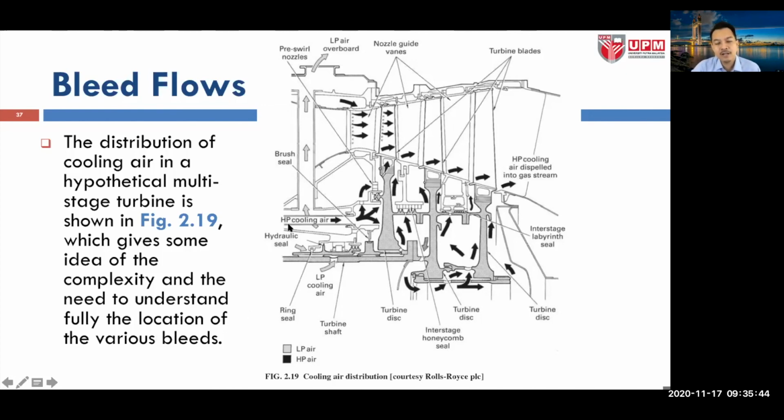Basically, the gas turbine engine designers, especially the internal cooling engineers, have to calculate the amount of high pressure cooling air that comes from the high pressure compressor, being supplied through the complex mechanism of the engine, and how much is going to be bled, in terms of the sizes of the cooling holes, the location of the cooling holes, and the respective temperature and pressure.